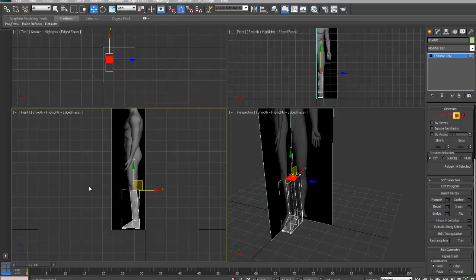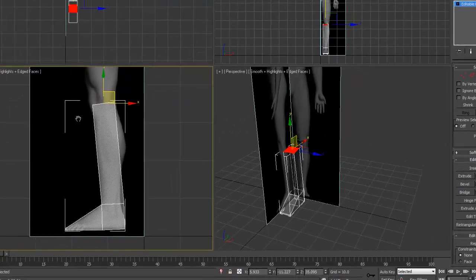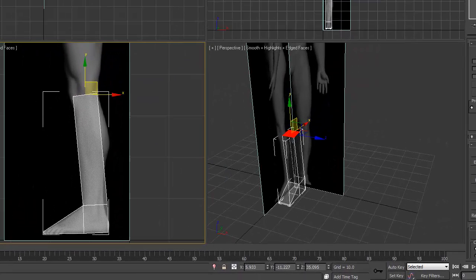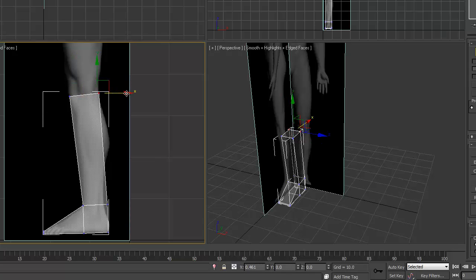So I'll just readjust a few verts in here just to make it a bit more clean. So I've gone back into vert mode and just drag them out. Don't push them too far out of angle. Just drag them out on the X at this stage. These guys down here, remember, you're grabbing two, you're grabbing one from behind. It probably needs to come in there a bit like that for now. Don't worry about all this. We add all that later.